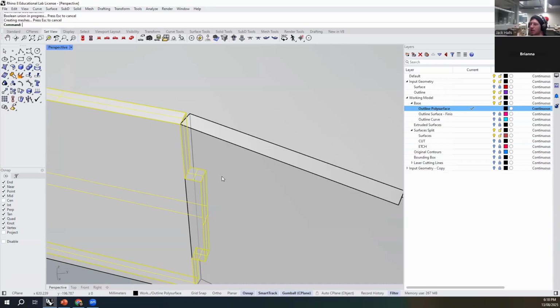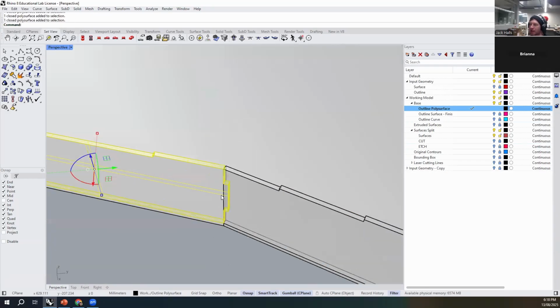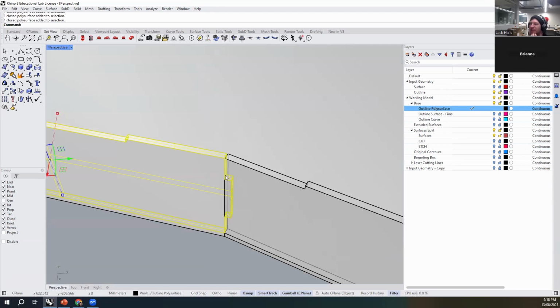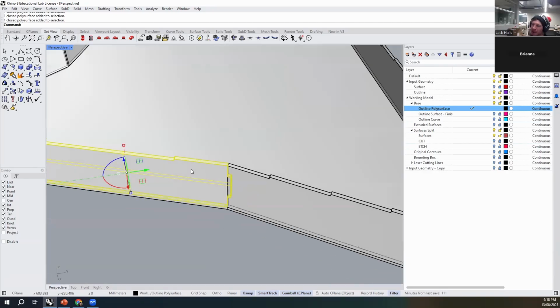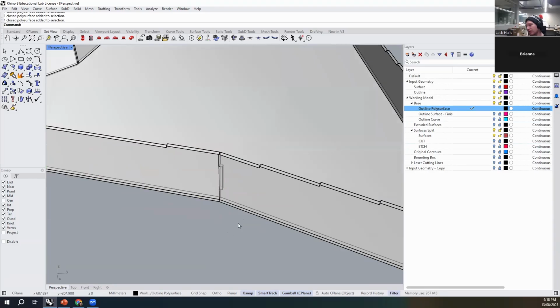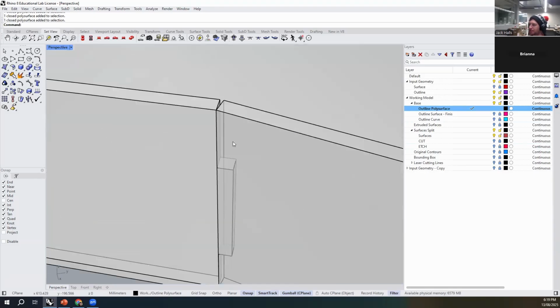And that's going to join them together. In Rhino 8, it'll automatically do something called merge all coplanar faces. So it'll merge the faces of those geometries. If you're in Rhino 7, you'd use the merge all coplanar faces command after the fact, and that will matter for extracting curves for laser cutting in a minute.